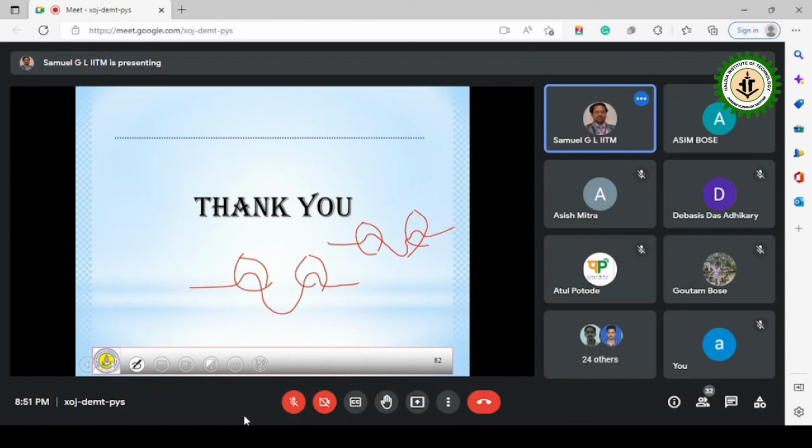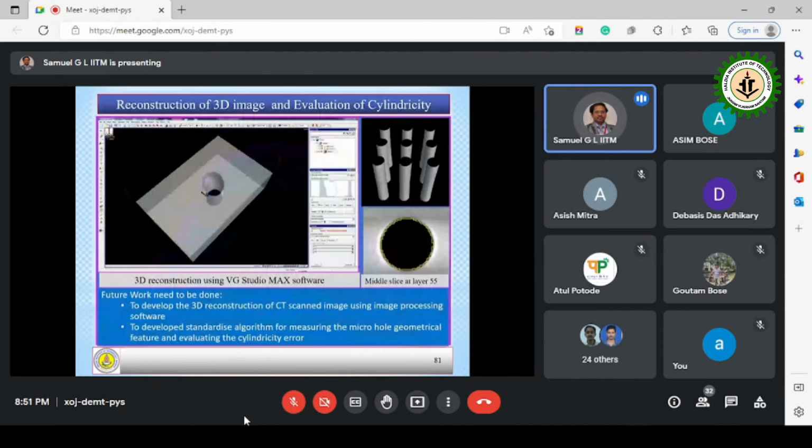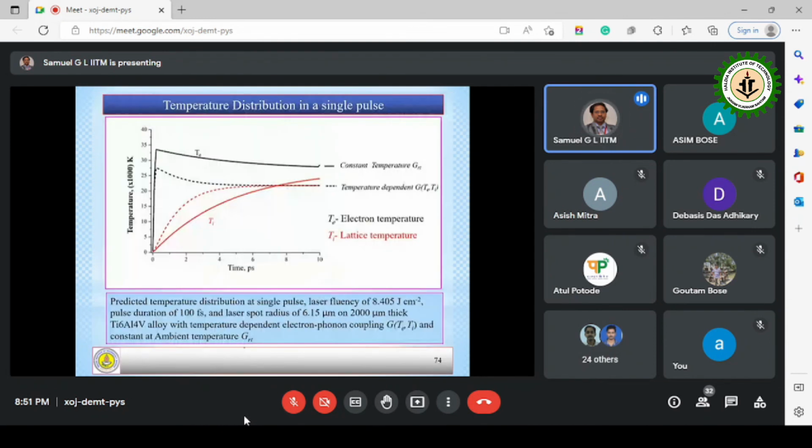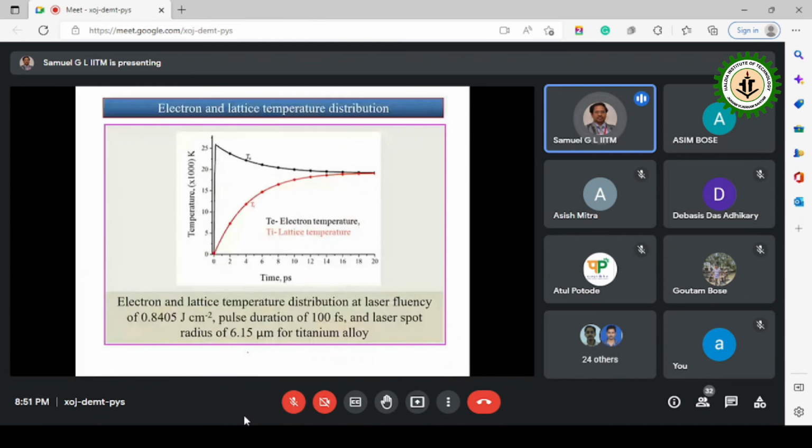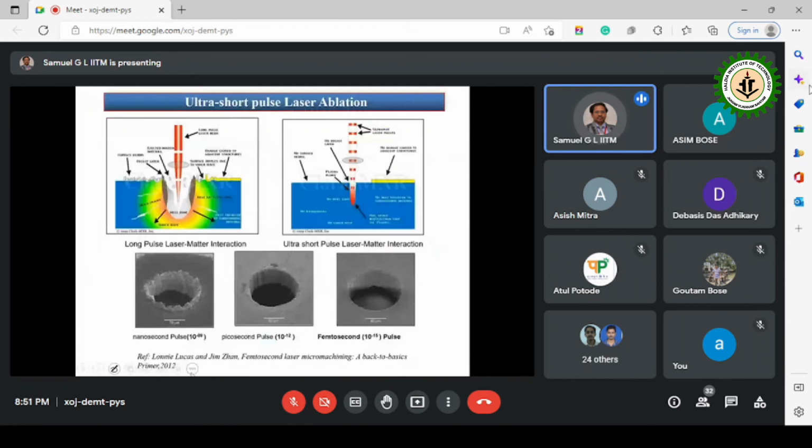Yes. So, is there any way that you can possibly eliminate it, or do you have to use another method of surface polishing? No, actually, when I showed you the profiles in the beginning to compare this phenomenon, you can see this is the way it will be. Now when you use a continuous laser, this will be even worse. With nanosecond, it is like this. With picosecond, it will be like this. With femtosecond, it will be like this, which is literally good enough for any practical purpose to be used directly.